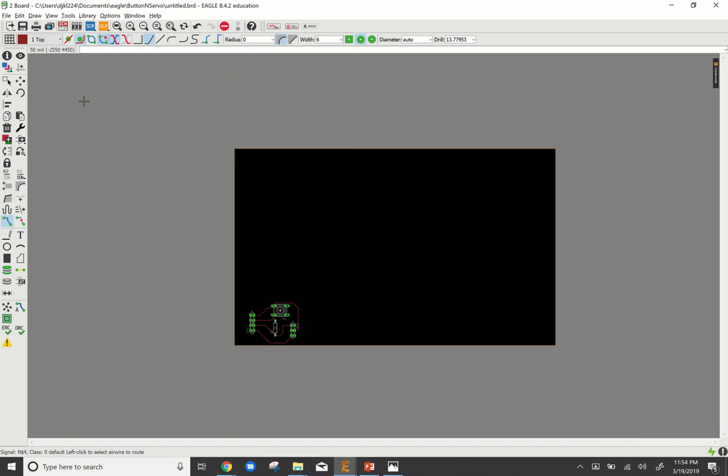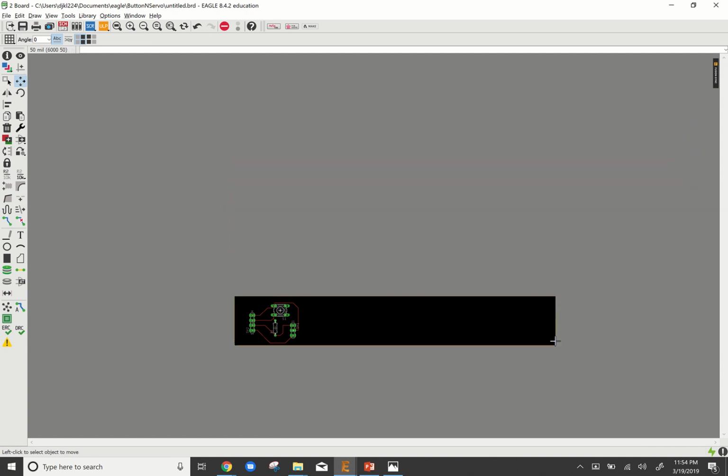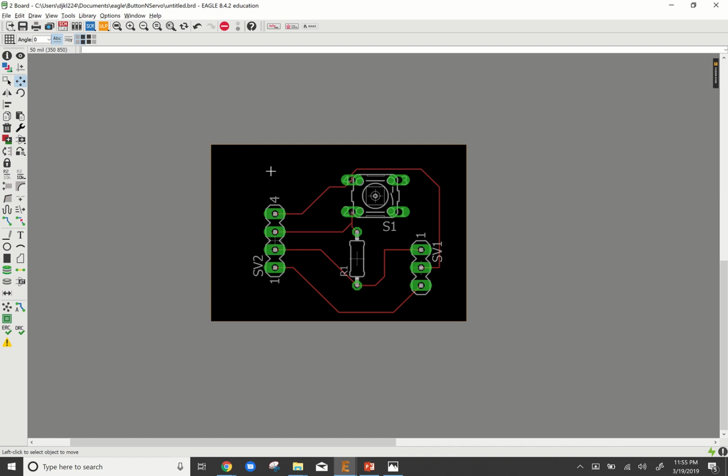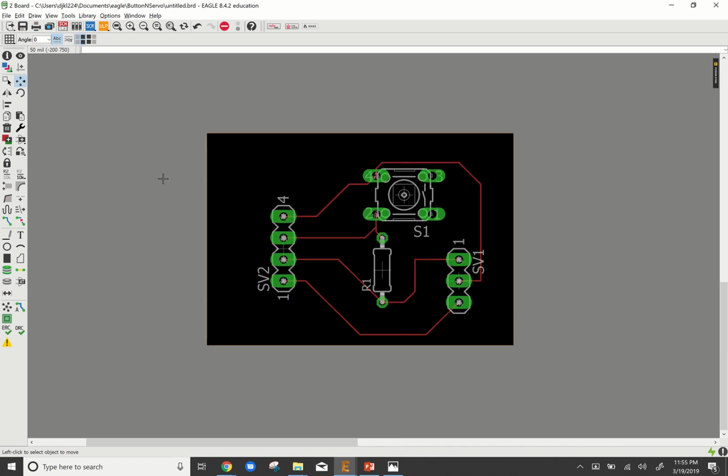So I can now sit there and adjust the size of this board. And if I was in industry, my goal here would be to get this as small as I possibly can. The reason is that the smaller it is, the cheaper it's going to make, or the more I can put on the board. And so if I was going to send this off to get machined, I would probably try to shrink this down as far as I possibly could. And so I'd bring this over to the edge, leaving just maybe a 1/16 of an inch or 1/8 of an inch, and then just sort of bring everything else close to where it was combined. And that would allow it to be, when I sent this off, a very cheap endeavor.